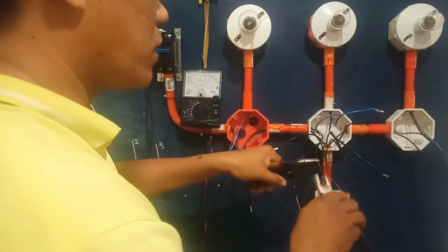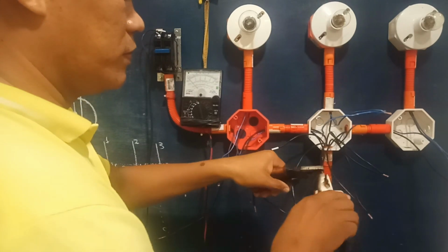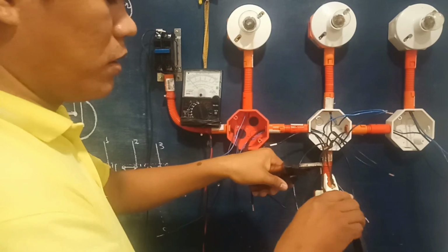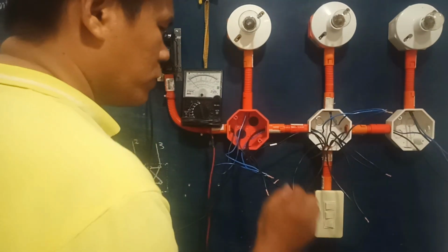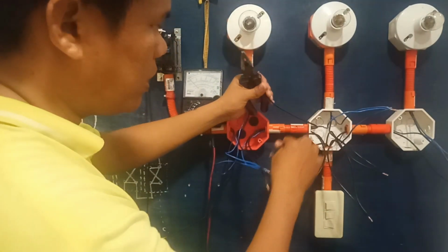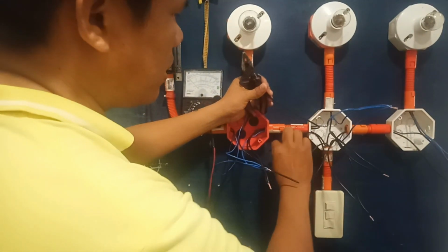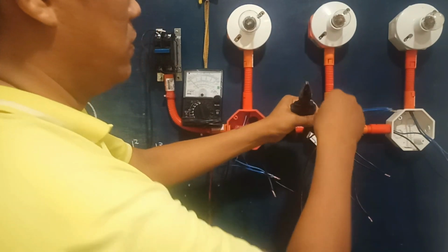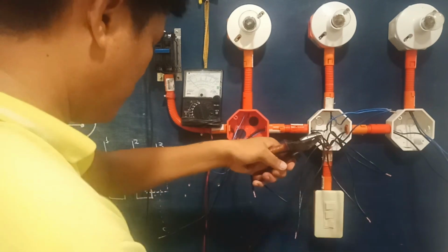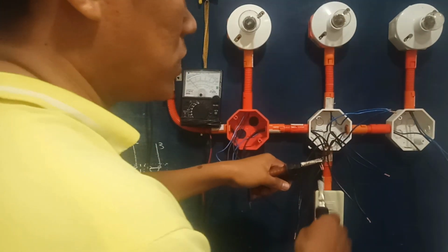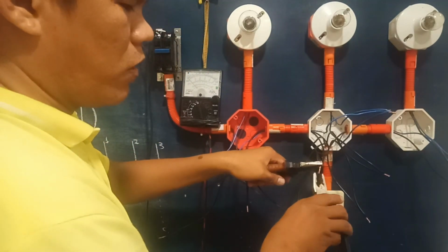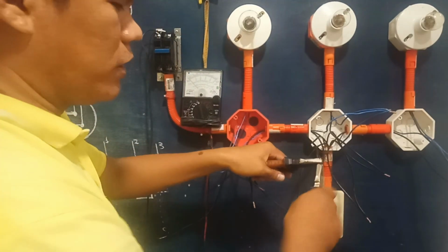This is the last cycle now, coming from the common terminal of our 3-gang single pole switch. So right here, this is the common terminal. We're gonna use this one, join together. So this is now the common terminal, the last cycle now, going back to the source line or line 2. Okay, I hope you can follow me, guys, right here.